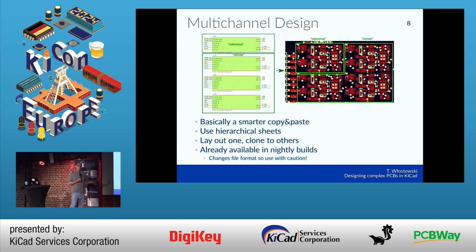You need to enable it in the advanced config. Check the documentation for that. Beware, it changes the file format. So if you add some multichannel areas, older versions of KiCad, including this one, will not read it.